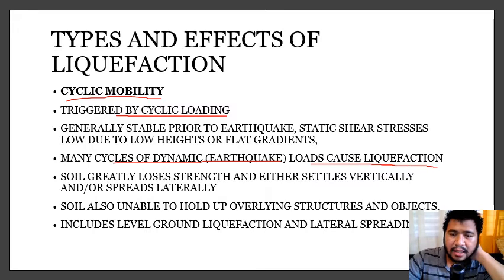And eventually, this leads to liquefaction. And since a liquefied soil has a very low strength, the soil can either settle vertically, in the case of level ground liquefaction, or it can also spread laterally in the case of lateral spreading.